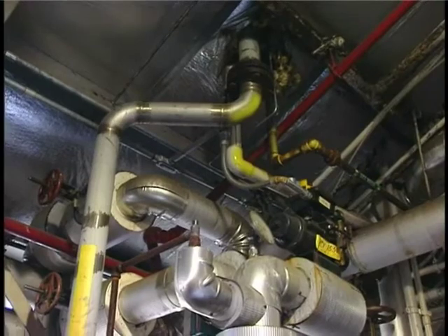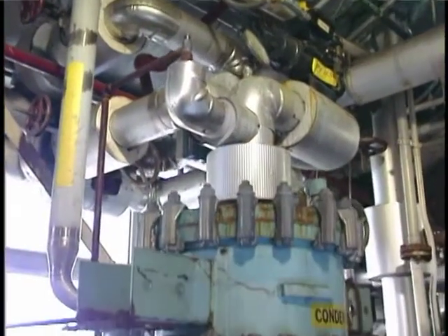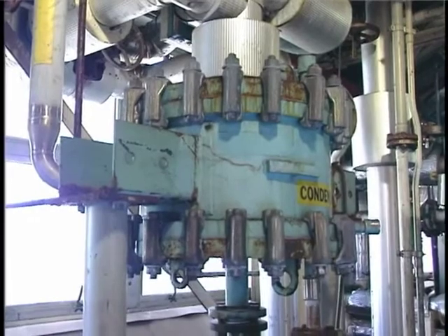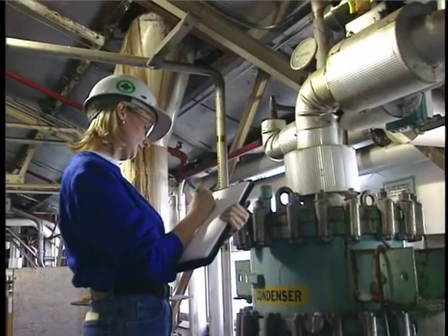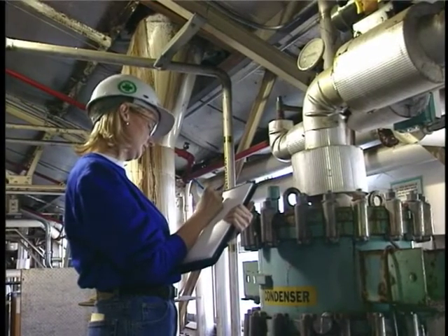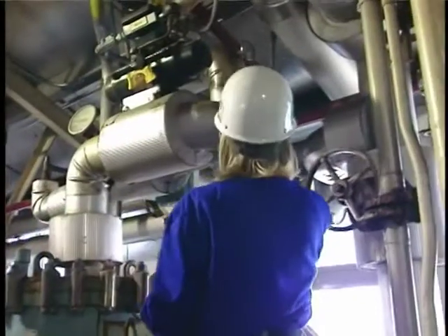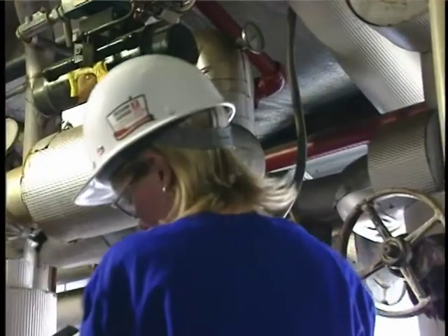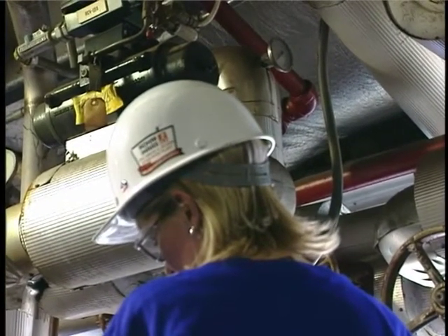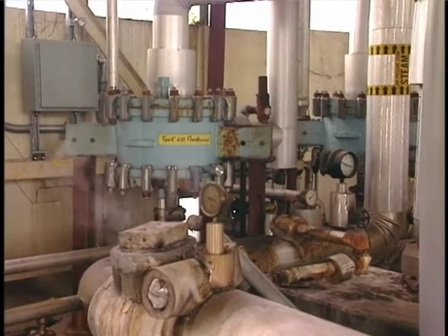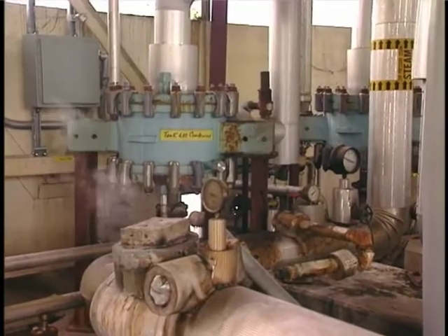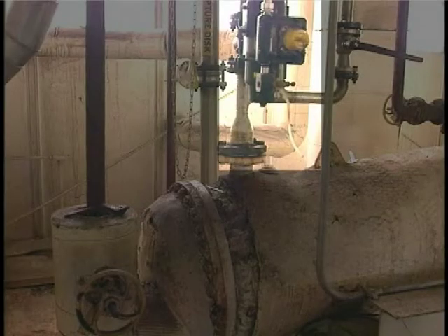The best indicator of the performance of a condensation system is the outlet gas stream temperature. Since the outlet concentration is equal to the vapor pressure at that temperature, increased outlet gas temperature would indicate reduced collection efficiency. If outlet temperature records are maintained, they should be reviewed to determine periods of increased temperature. Short-term increases are usually associated with frost removal, and the records can be used to determine the frequency. A gradual increase in outlet temperature will occur if ice or frozen organic compounds are accumulating on the heat transfer surfaces.